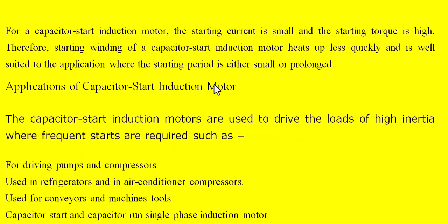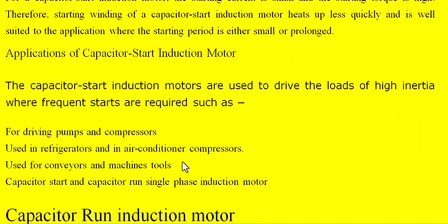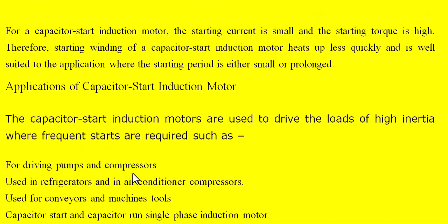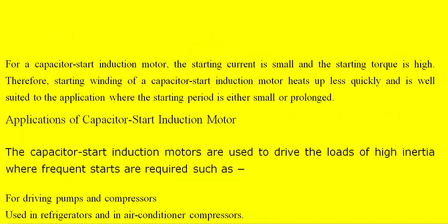And the applications of the capacitor start induction motor are like this. One is for driving pumps and compressors. The other is that it is also used in refrigerator and air conditioner compressors, and it is also used for conveyors and machine tools. And this motor is used where the starting period is either small or prolonged.